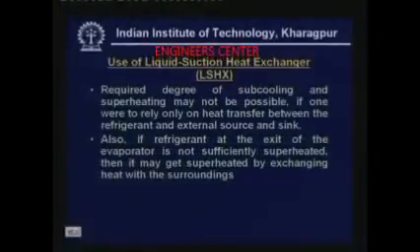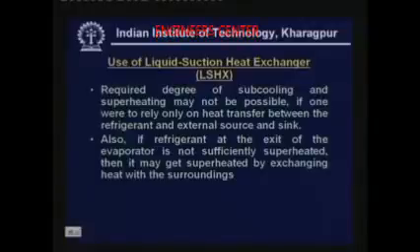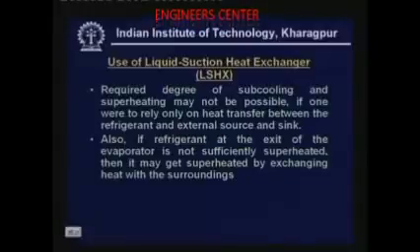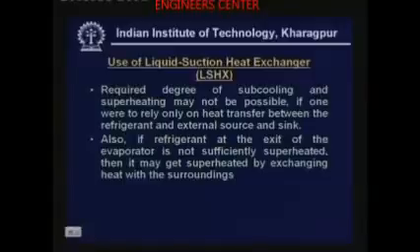So that is what is mentioned here. Required degree of subcooling and superheating may not be possible if one were to rely on heat transfer between the refrigerant and external source and sink, and also if refrigerant at the exit of the evaporator is not sufficiently superheated. This is another reason why we need a liquid suction heat exchanger. If the exit is not sufficiently superheated, then it may get superheated by exchanging heat with the surroundings, which as you know is useless superheating.